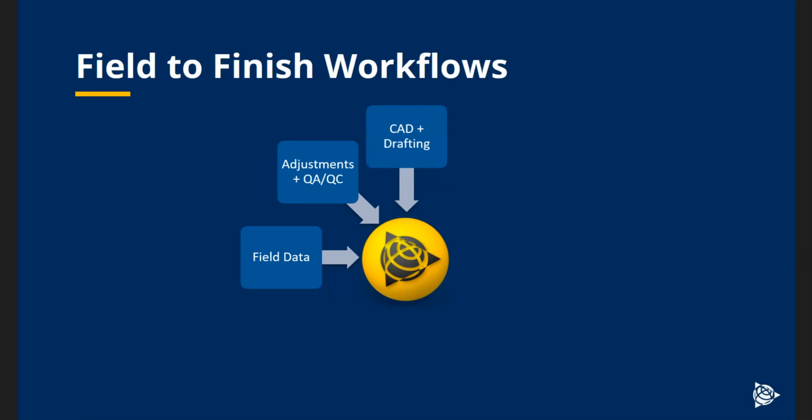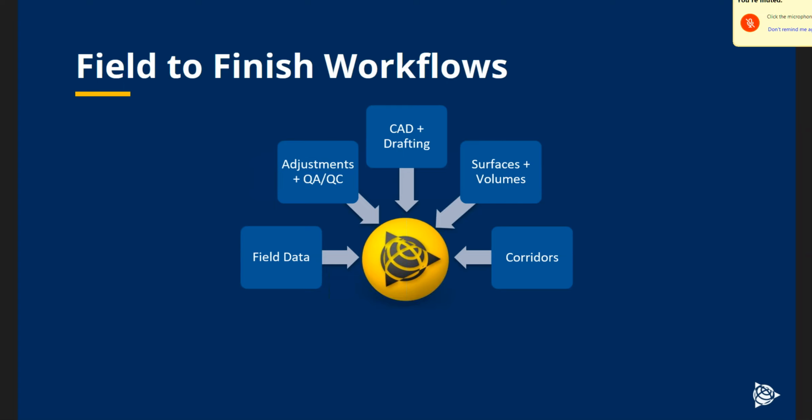You can do drafting in the software or bring CAD data into it. Surfaces and volumes can be calculated, and corridor data can be worked with. You can create corridors that can be imported and exported to our field systems and worked with for roads and different kinds of pipelines and whatever it happened to use.